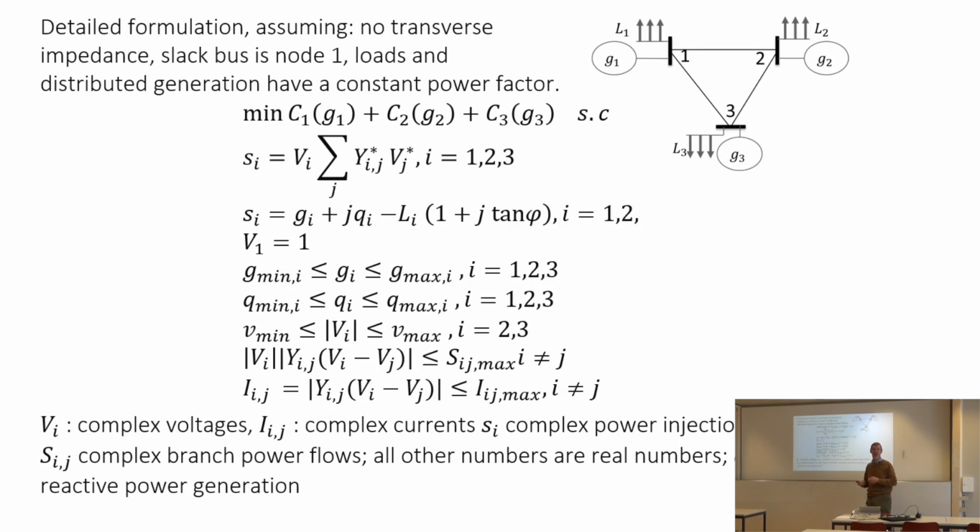Some will. In particular, modern machines that are using DC AC inverters very often are able to work through a large range of voltages. But there is a minimum below which it will not work, and also a maximum. If the voltage gets too large, some of the things might not work. A classical example is the elevators.